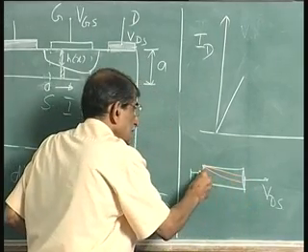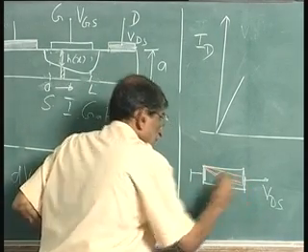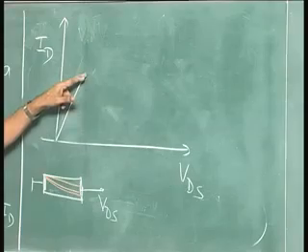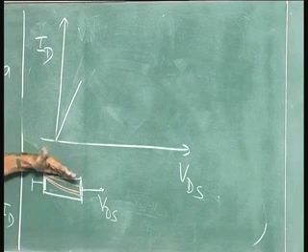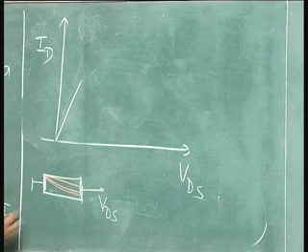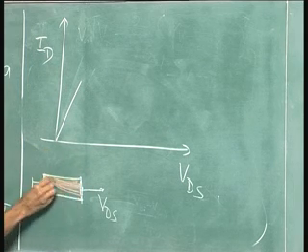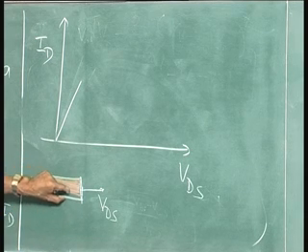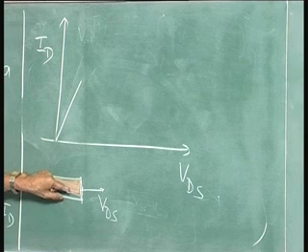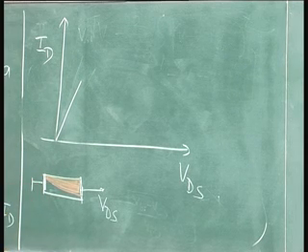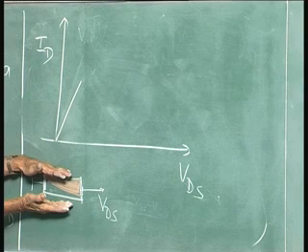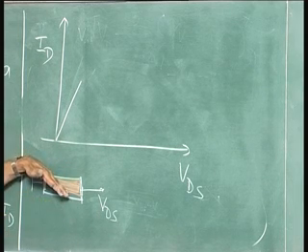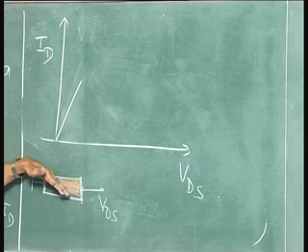like that. Each increase in drain voltage as we move down here will make that region, at this point, have the channel thickness varying like that. What happens to the resistance? If I take a resistor which is constant and keep on reducing its cross section in that fashion, the resistance actually increases.